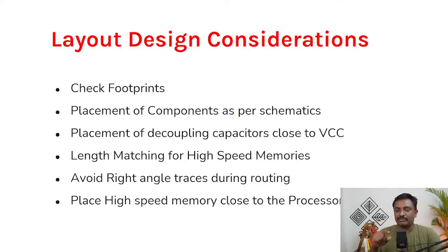Placement of decoupling capacitors has to be done very close to the VCC pin of the microcontroller, a DSP processor or an FPGA. Length matching for high-speed memories: whenever you connect high-speed DDR memories with the microcontroller, the lengths should be the same. Otherwise, there will be a propagation delay. In order to match the length, they do serpentine routing, intentionally introducing a delay on this line.